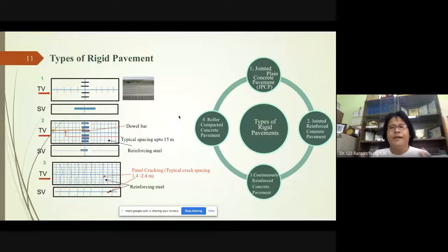Whatever the case may be, I have mentioned four different types of pavement as of now. Regardless of these types, the most important thing to understand is that the construction of these pavements will be done with a concrete mix. The only difference is whether one type of concrete requires a low slump and the other requires no slump, a very stiff kind of mix. Therefore, the formulations of the concrete mixes are slightly different from each other.